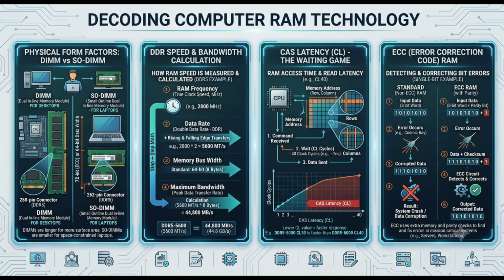Okay, let's walk through the math from the source notes on this because it is brilliant. We are using what they call even parity. The rule is that the total sum of all the ones in that 9-bit package must constantly remain an even number. Exactly. So let's say our initial 8-bit byte of data is 1 0 1 1 0 1 1 1. Okay, so we count the ones. There are 6 ones in that byte. Right, and 6 is already an even number. Therefore, the memory controller automatically assigns that 9th parity bit a value of 0, because the total sum remains 6. It stays even. Perfect. But what if the byte was almost empty?